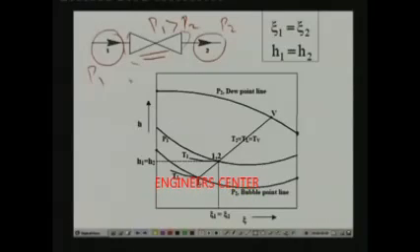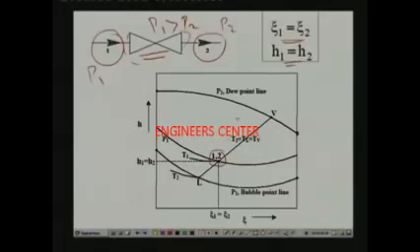If you apply mass and energy balance, you will simply find that the composition remains constant and the enthalpy also remains constant. So, if you show this throttling process on the enthalpy composition diagram, you will find that both inlet and exit points are at the same point. That means they are identical, because enthalpy is the same as this equation shows, and concentration is also the same.